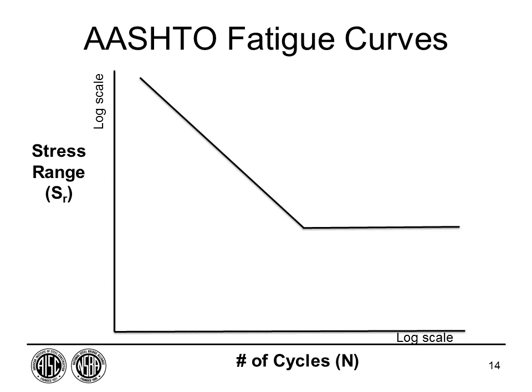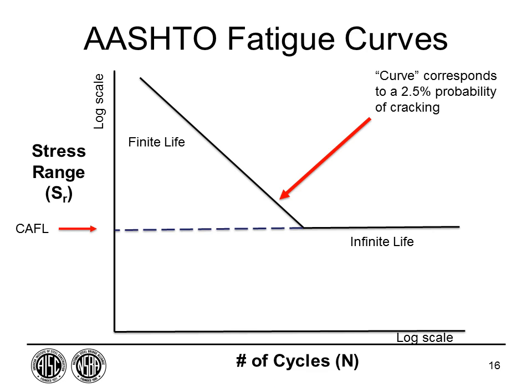So this is our common fatigue curve. A couple of things to look at here. Our vertical axis is stress range. Our horizontal axis is number of cycles. Now that's the infinite life region, the constant amplitude fatigue limit I discussed. Basically it says if my stress ranges are down in this region below it, I would never intersect a curve with time, right? This is cycles, so that's kind of like time. And I could expect to have infinite life. That's a good place to be.